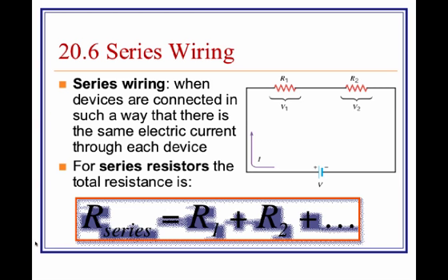In a series circuit, the resistors add together. So here we have R1 and R2. The equivalent of R1 and R2 would be the two resistances added together. We also have a voltage drop, so that's some energy used across resistor 1 and resistor 2. That voltage drop, those two combined, is equal to the voltage provided by the battery or power source. So here's just series circuits.